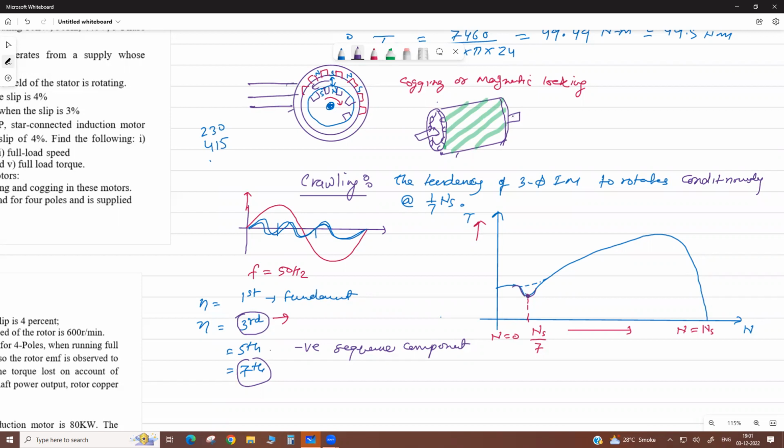Now, if your motor is loaded, with a mechanical load connected, then when we start the motor, it will accelerate and continuously rotate at this speed. It will not overcome the dip, not reach here. Generally, this is the operating point of your motor, where your motor operates. This should be your RPM. But when we accelerate, the motor will pass through this curve and stay there.